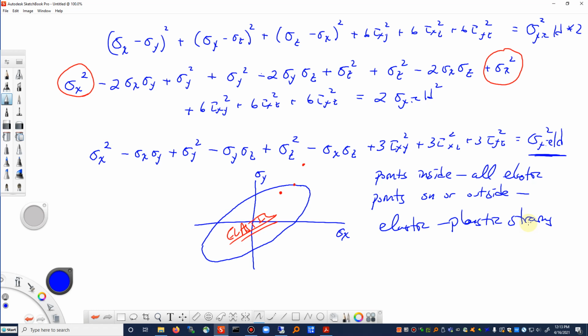What we're going to go through today, I'm going to probably represent this as a circle because it's easier to draw, but the same concepts apply. The numbers are a little different, the calculations are a little different, but what we want to emphasize is the concepts of multi-axial cyclic plasticity for fatigue analysis. So I'm going to take a shortcut and just draw a circle to represent my yield surface instead of these ellipses all the time. You can always take an ellipse and, with the appropriate coordinate transformations, turn it into a sphere or a circle. So instead of drawing this hyperellipsoid, I'm drawing a yield surface that's circular in shape that could represent a hyperellipsoid. But again, anything that's inside of it is elastic. Anything on it or what could be outside of it has elastic and plastic strains.